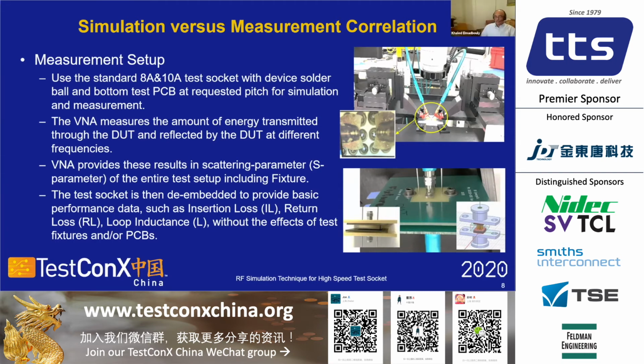Yeah, I answered the question about the TDR rise time. Usually our standard is 25 picosecond. Sometimes we'll go faster, 15. Sometimes we'll go slower to 35, based on the customer setup. That's for the rise time. And for the first question, he's saying, how do you define the PCB material?